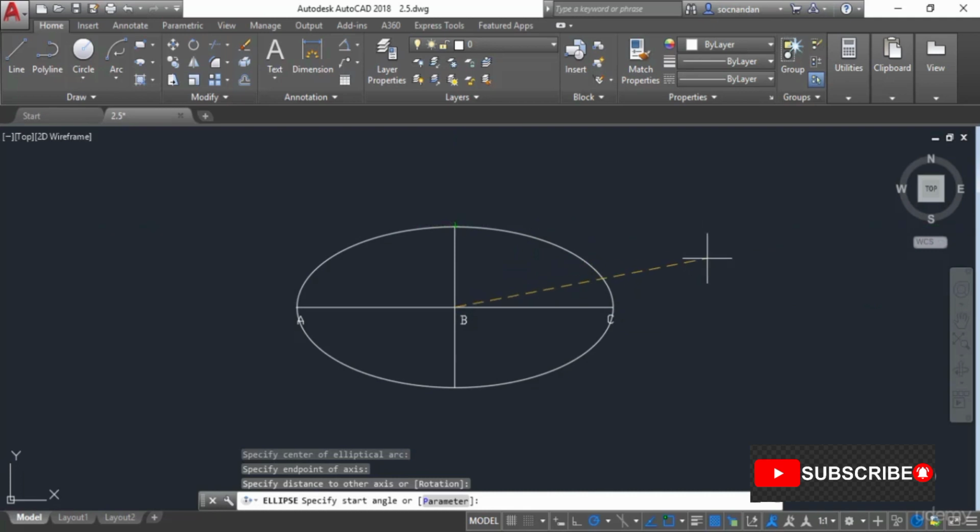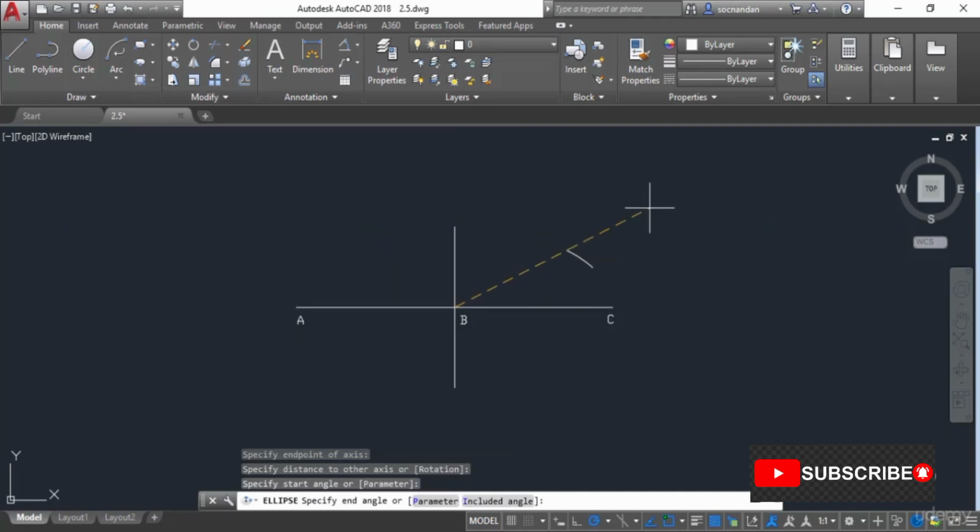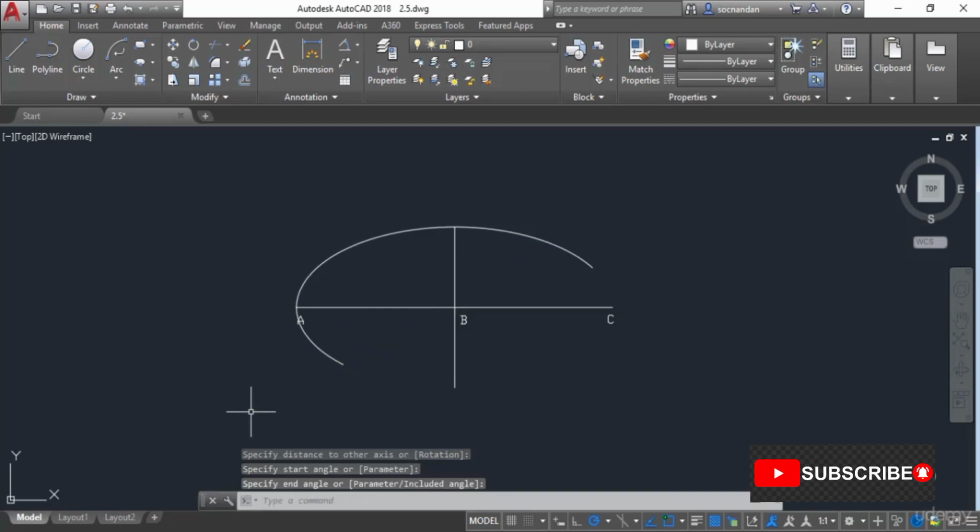And now you need to start the angle for the elliptical arc. So click anywhere in the drawing area, and that will be the starting point for our elliptical arc. And as you can see, now our elliptical arc is being made from that point, and now you can click at any other point to end the elliptical arc, or you can also add the included angle directly on the command line. So I'll simply click here, and here we have it, the elliptical arc, which is simply a part of this complete ellipse. So in this way we can make ellipses and elliptical arcs in AutoCAD.